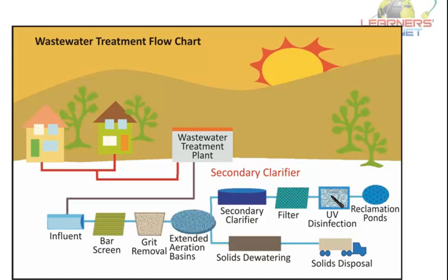So disinfection is frequently built into the treatment plant design, but it is not effectively practiced because of the high cost of chlorine or the reduced effectiveness of ultraviolet radiation where the water is not sufficiently clear or free of particles, and that is why primary and secondary processes are of more use than the tertiary process, right?